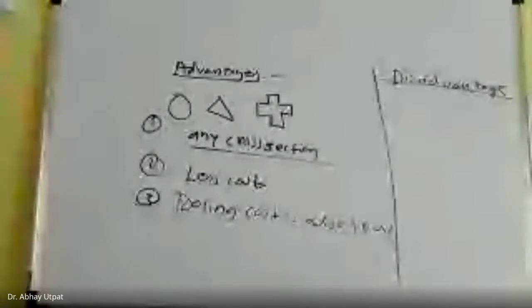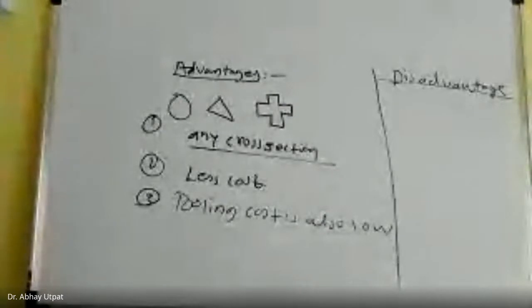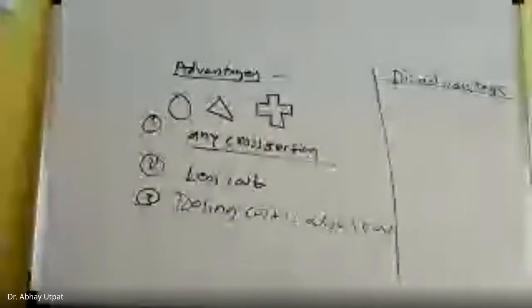So the principle of extrusion molding I told, then there may be different types of extrusion molding I told: solid extrusion, hollow extrusion and co-extrusion. That I have also explained. There are two types of extruder. One is melt extruder and another is plasticizing extruder. I hope you have written these two types. Melt extruder consists of providing the plasticized plastic.